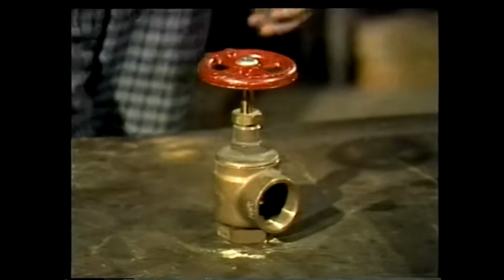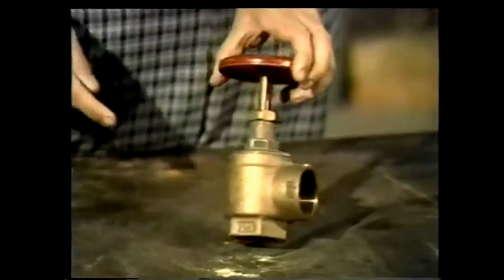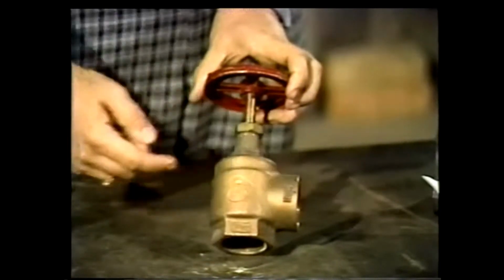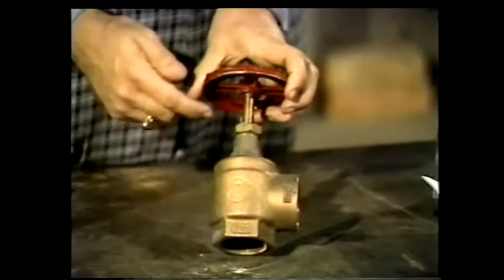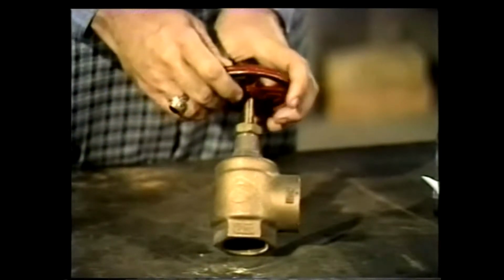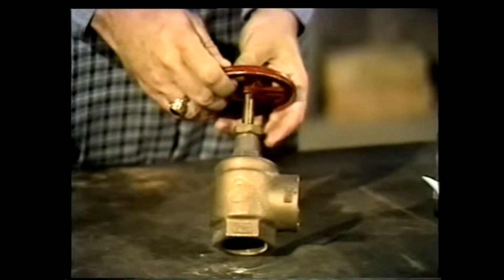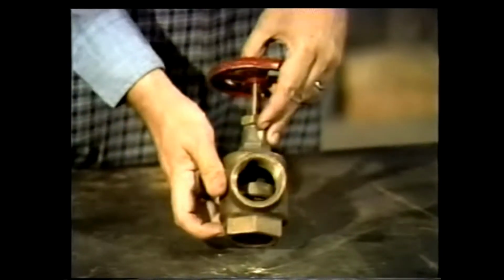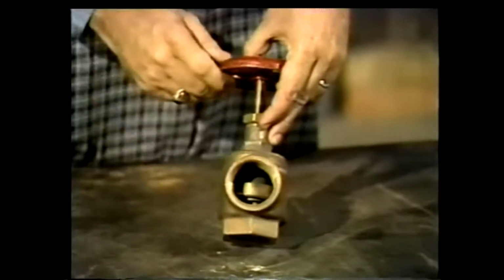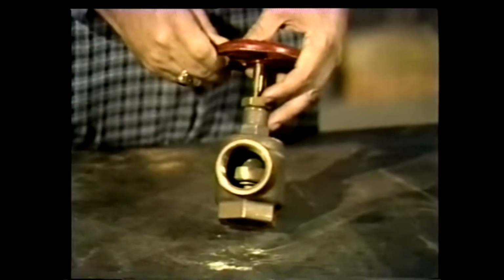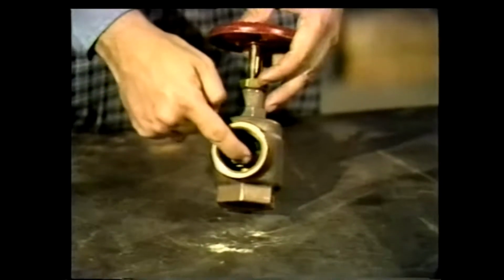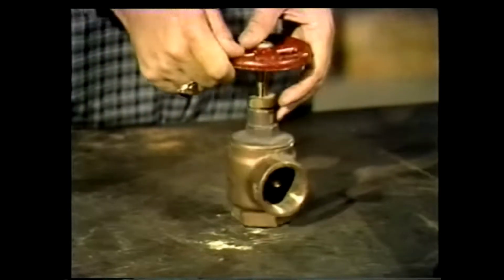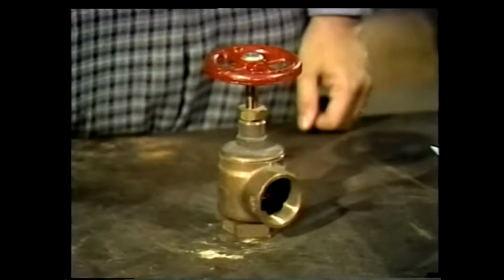Another body type is the angled globe valve. This design helps to eliminate the need for adding elbows to change the direction of flow, thus reducing the number of joints. The fewer number of joints, the fewer points where leakage can occur. Now, both of these surfaces are built to provide a tighter seal for positive seating than is found on a typical gate valve. The shape and arrangement of the disc on a globe valve is varied depending on the type of service it's designed for.